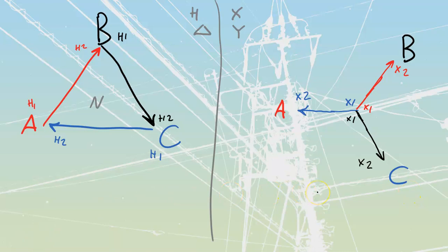Beautiful. Okay. We've got all of the X1s, all of the X2s that are now laid out onto this diagram. This is once again that really, really weird one where on the low voltage side, we're using the C phase over here to go and feed the A line. We're using the A phase to go and feed the B line. We're using the B phase to go and feed the C line that we are going to go and have off of that.